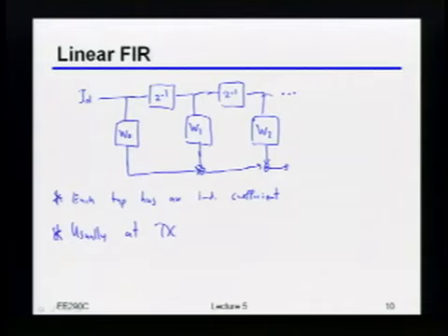Anybody know why it is that you usually do this at the transmitter, and not the receiver? Yeah. Also, you don't need an ADC. It's probably easier. Okay, so you said no ADC. That is true, although that's probably not the fundamental reason. You can easily delay it by using flops. Ah, there we go. It's actually the delay that's the biggest trick.